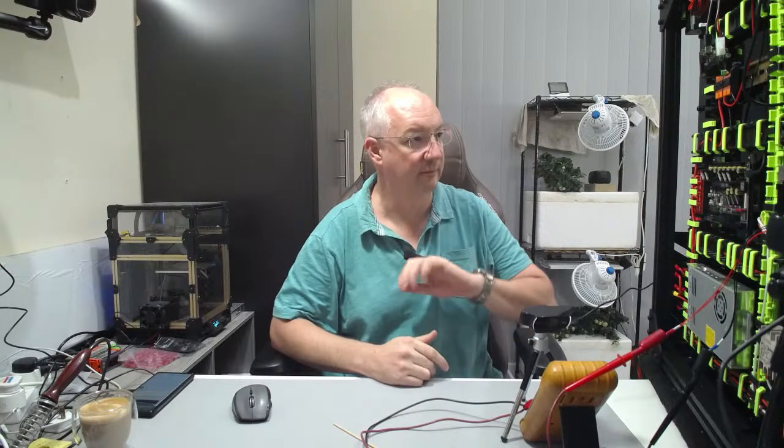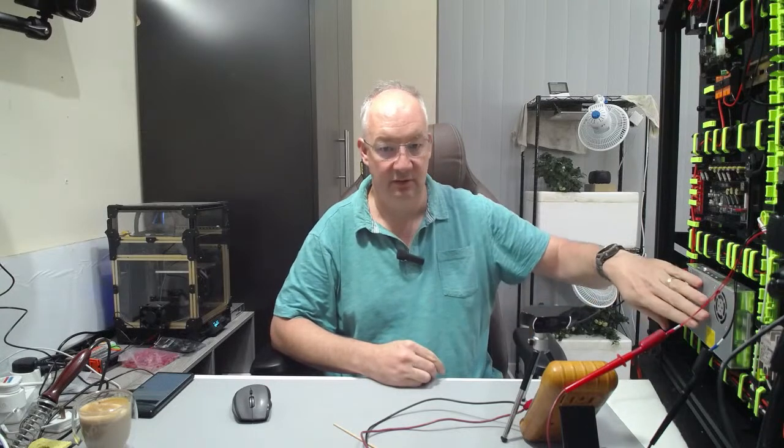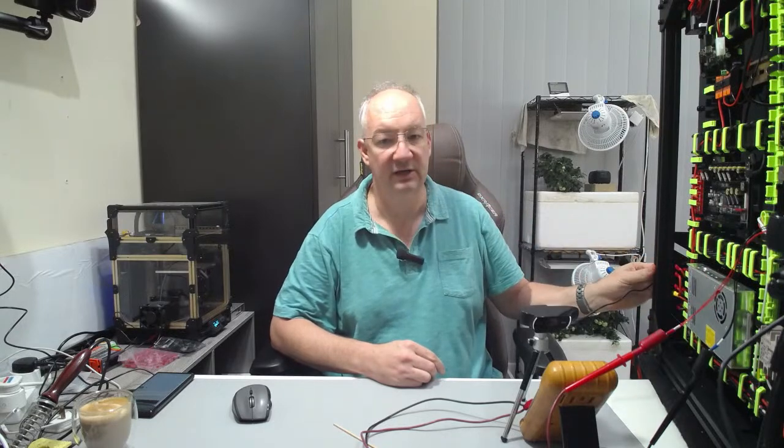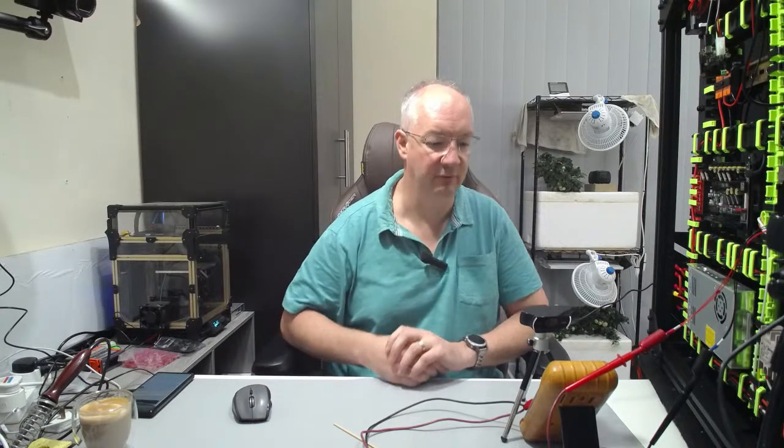that's all I'm going to do from a wiring and a power perspective. What I will tell you is on the 24 volt power supply, I'm actually going to set that voltage at 24.2 as well, give or take. So about 24.2, and make sure that my power is sufficiently above 24 volts, but not too far.